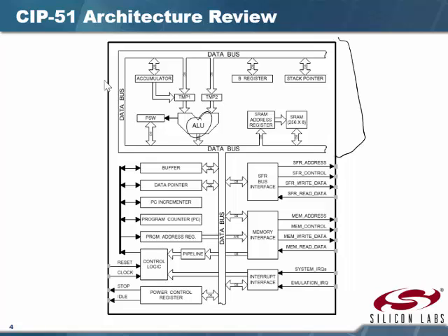Now that's fed directly into it is the accumulator. You'll find that a lot of our instructions, such as add, multiply, divide, some of those instructions have to go through the accumulator. The accumulator, and that's actually register A when you're writing assembly language, is called the accumulator. That's our primary register. Then we have over here our B register, which we use on occasion. That's just another register there.